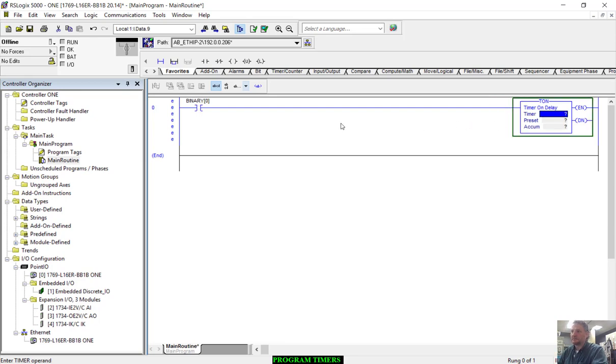I will also not accept any latches or unlatches in any of my programs. These are latches. This is a latch output. This is the unlatch. This is a form of programming that I see from time to time with machine builders. It's a solution that works, but it's very complicated. It makes for some very difficult troubleshooting.